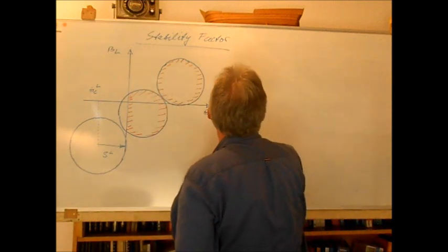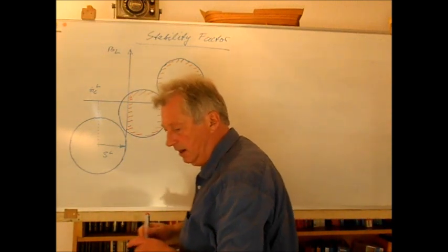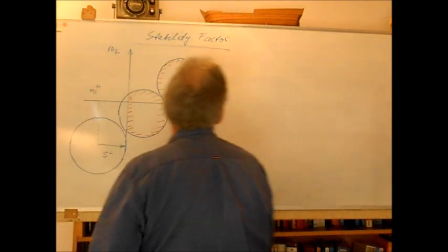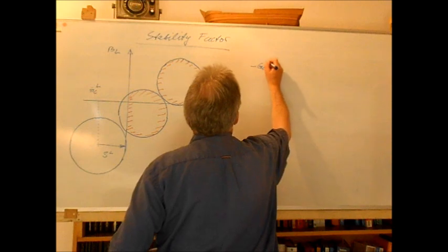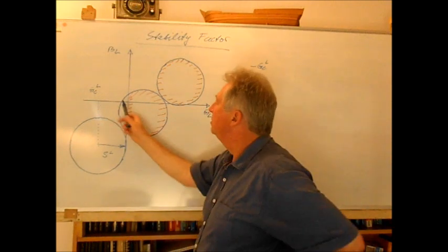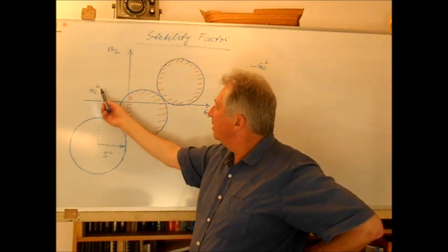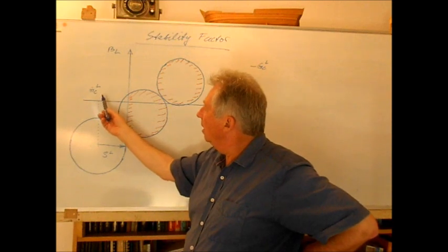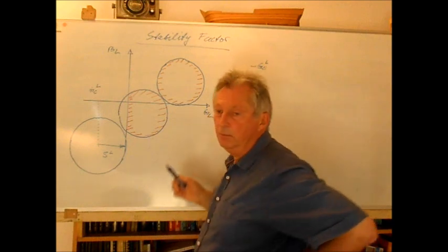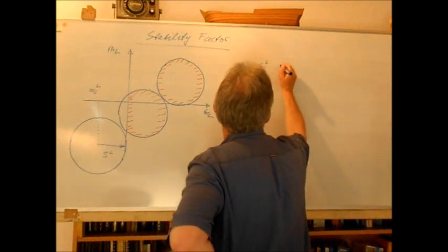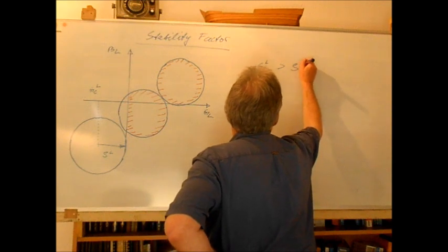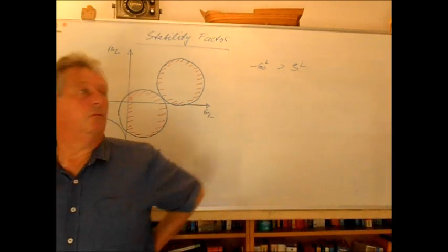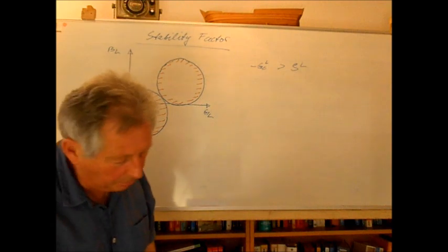As a condition for this we can say: as soon as the center moves into the left half plane, the center becomes negative, so minus G_L center would be positive, and as soon as this is greater than the radius of our stability circle, we will in principle have no problems.